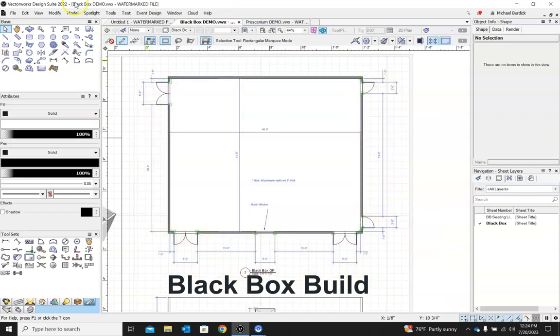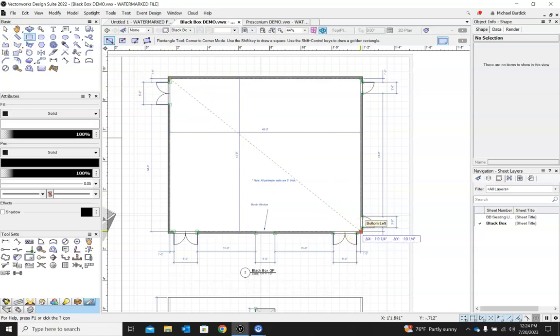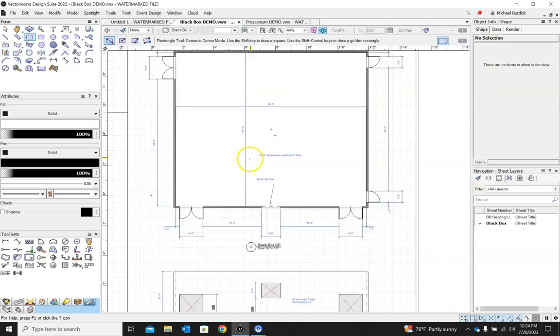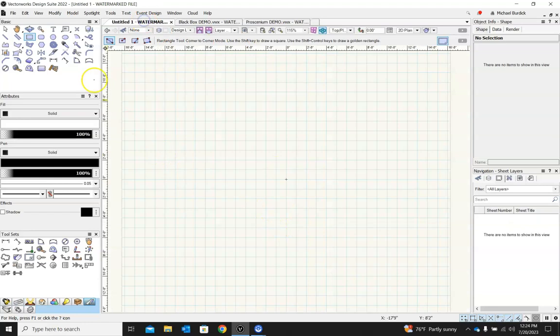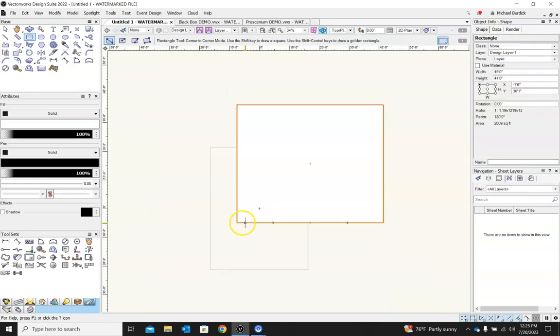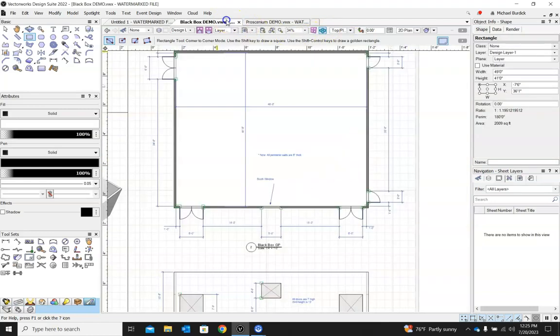So you'll see on here, what I probably want to do is simply draw out this floor first, right? You'll see on here that's 49 foot across by 41 foot high. The other good thing about this exercise is it'll just get you used to reading dimensions and kind of figuring out how a lot of these things look. So I'll draw my first box. I'm on a clean page now. I'll tab in. It was 49 foot wide by 41 foot tall. So there is the basic box.